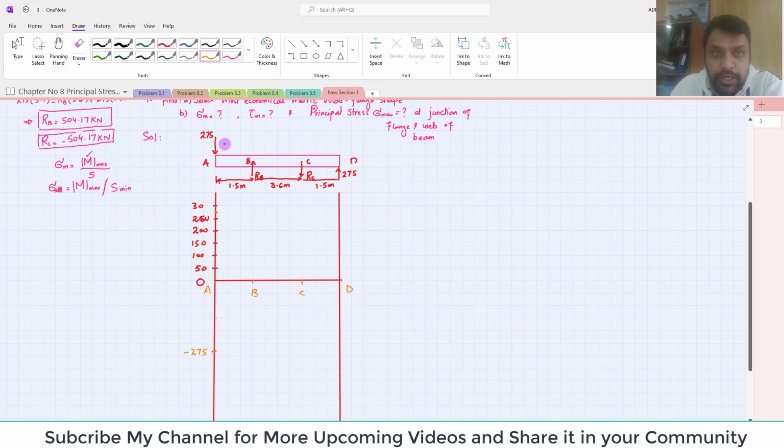So from A to B we can see there is no other force, so the shear force will remain the same till point B. So you can draw a horizontal line as well, clear. Now at point B there is a force that is 504, and that is upward. So 504 minus 275 will yield you 229. So 229 will lie somewhere here, so I will draw a vertical line from this point, so it will be this point.